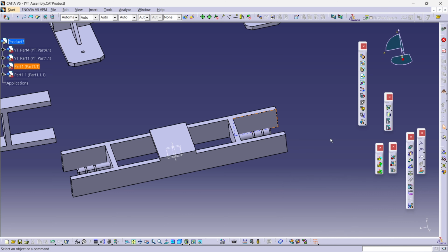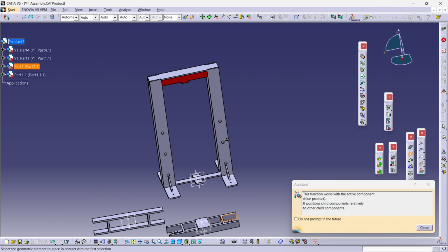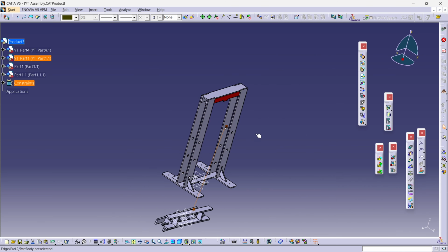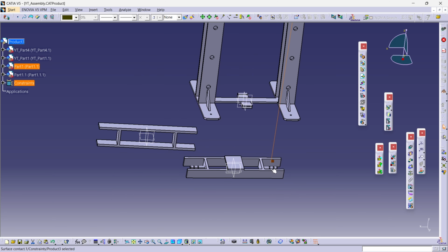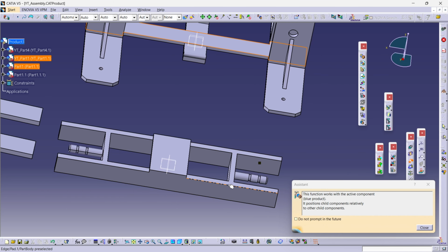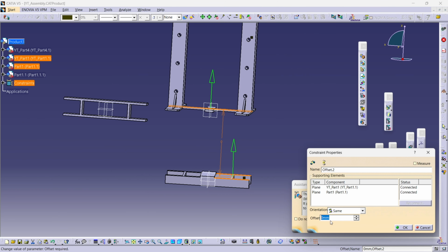Oh, there's no coincident for now. We'll go for contact. So this contacts with the other surface of this, right? And that's our contact. And next is the offset. We're going to use the term called offset. As I mentioned earlier, from the below surface to the top of this, the offset is 645 in negative. So we're going to use that.